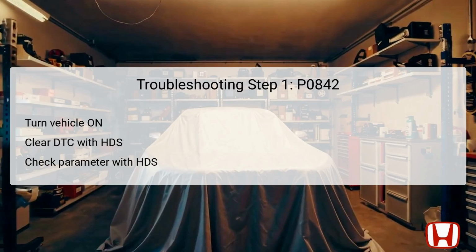If the conditions do match, the technician knows that the failure is confirmed and can proceed to the next troubleshooting step. If the parameters do not match, this indicates a possible intermittent failure that might stem from poor electrical connections.